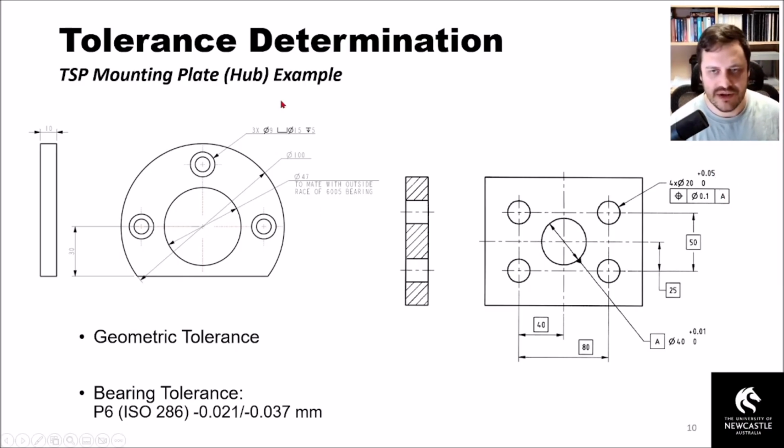All you would simply need to do for this example, for your holes up here, is just put in something similar to this underneath when you do your hand sketch, obviously with all the dimensions and the like on it, and you're going to use that central hole as that A datum plane. So we're using the positional for both the cylindrical and planar coordinates here. What you could also do, if you went back to your previous example, is use a coaxial geometric tolerance, which is essentially two circles in each other. But I'm quite happy for you to use the positional for both.